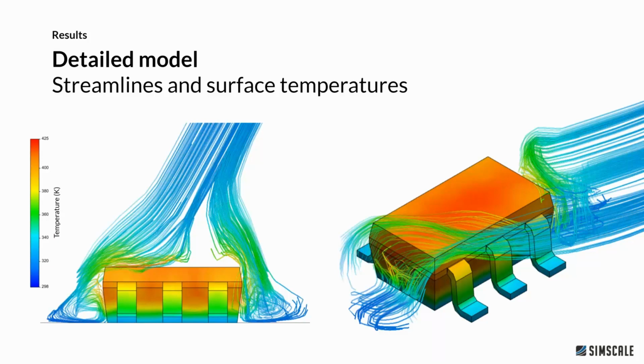A lot of technology companies are using thermal images in test environments to really get some insight into the actual results. The problem then comes when they want to reduce their operating costs, and they want to use CFD. And they go, okay, I've got this thermal image and I want to compare the CFD results to this thermal image. If you've used a resistance network, then that's not going to be correct. If you've used a simple model, then likewise, that's not going to be correct. If you're after comparing surface temperatures, you've only got one option really, and that's to use your detailed model.